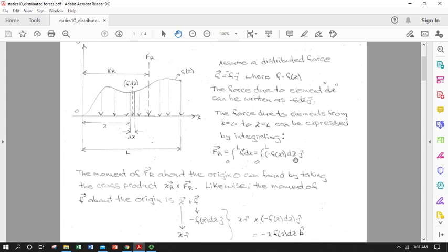So once we completed our integral and got an expression for F sub r, which is going to be a single number, when we integrate from a definitive point to another point, we end up getting a single number. So we'll have a single value for F sub r. We're going to know it's pointing downwards in the y direction, but we don't know where we would need to place it. The way we do that is to look at the effect of equivalent moment.